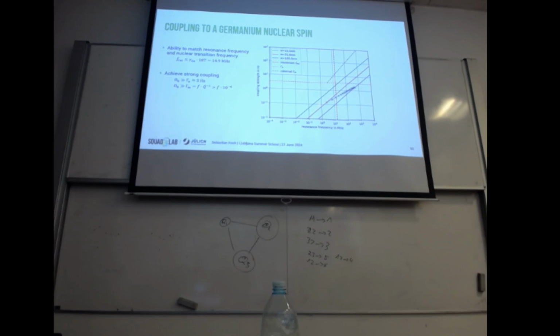And you see that although the coupling increases, the frequency of the resonator also increases, but it increases more than the coupling. So what we actually get is that the curve here is flatter than any of the fundamental mode curves. This means that, unfortunately, any increase in the mechanical mode won't help us here.